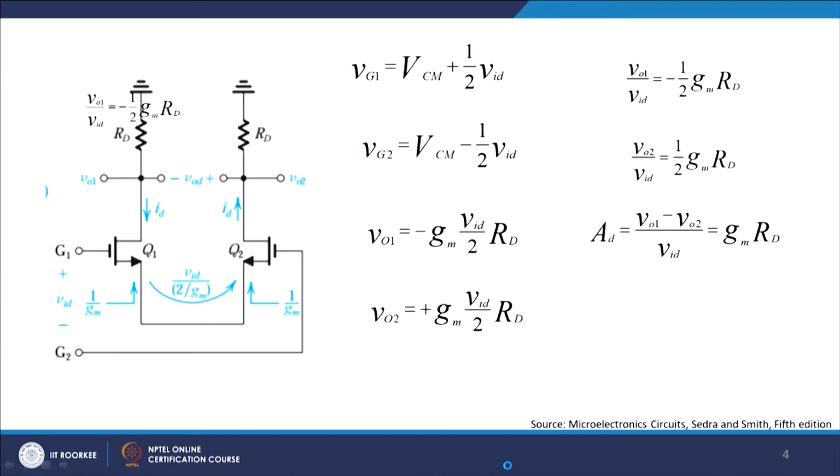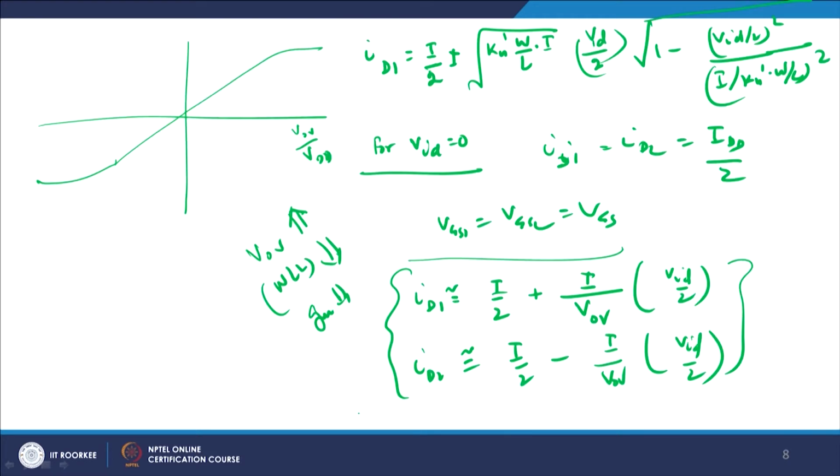So, as I discussed with you just now, if I do a simple design here, which is basically a half circuit design, I can show you that using this half circuit design we can actually do it. What is a half circuit? Half circuits are a very standard methodology used in analog circuit design or mixed signal design, where we assume that since the ground and power supply are the same for both arms, I can divide the two arms into two parts, find some important terms for one, and do a complementary equation for the second one, assuming that they are perfectly symmetrical with respect to each other. These are known as differential half circuits.